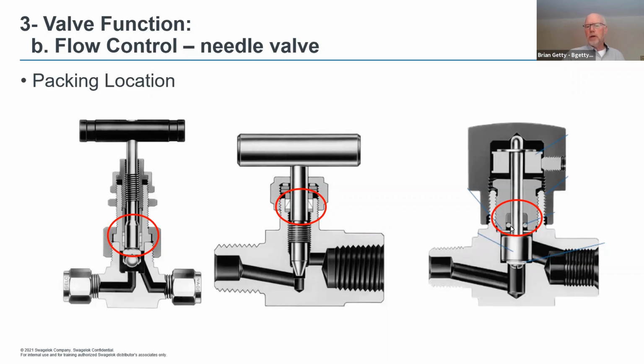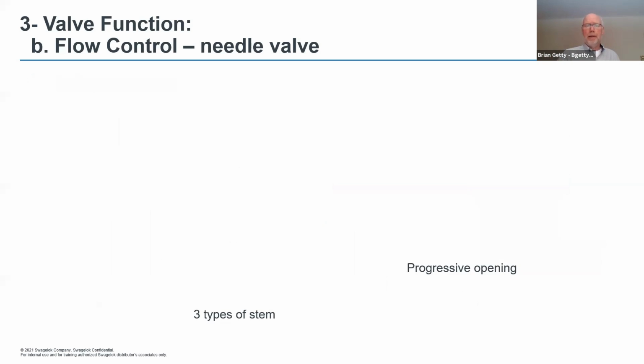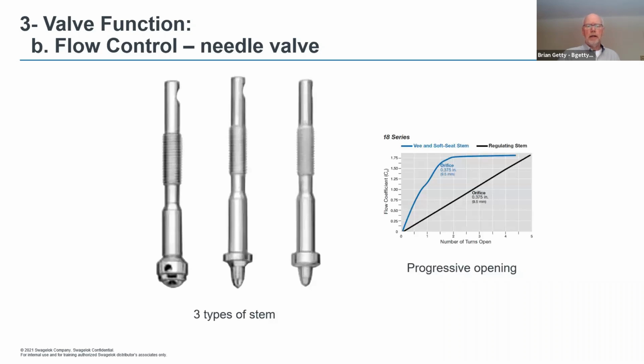Another application, as you can see here, is actually using an O-ring to create a seal around your stem. Is that O-ring going to be attacked by your system media? All important things. You have to look at those things. Sorry about that, I'm having troubles with my slide here. Hang on. Oh, there we go.